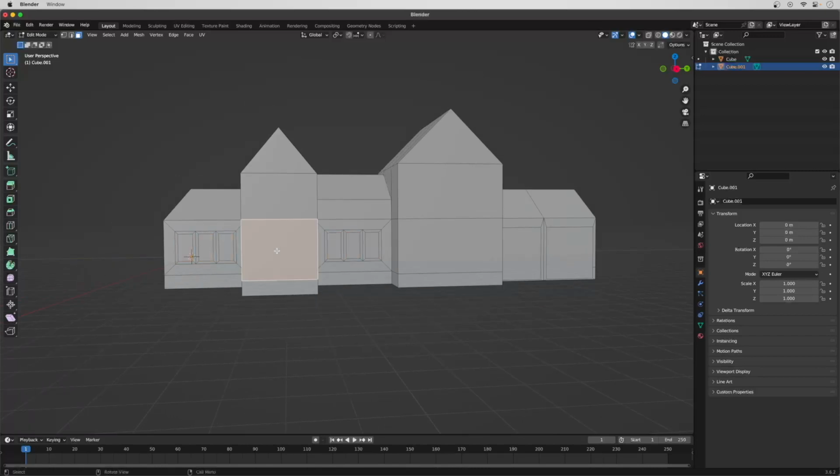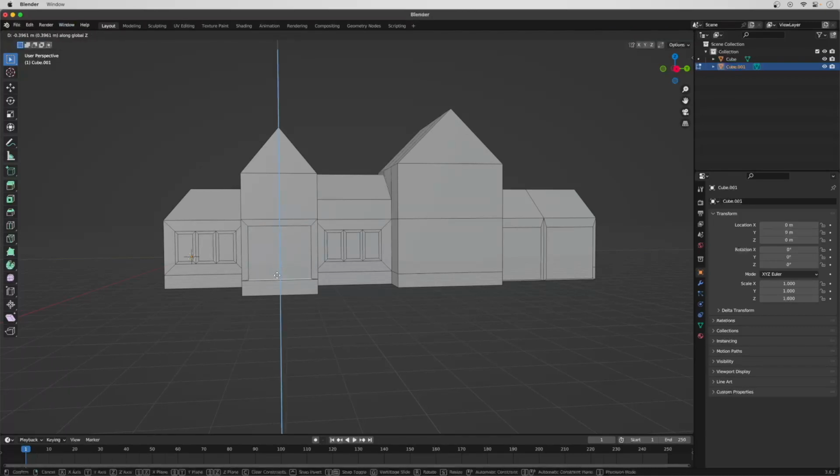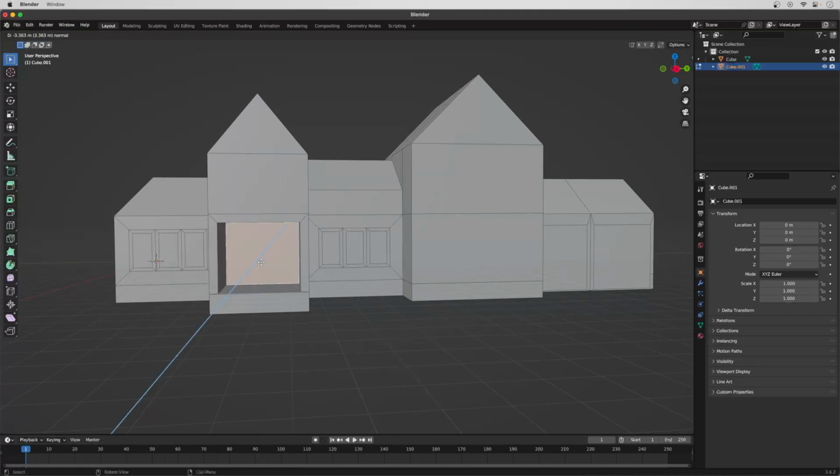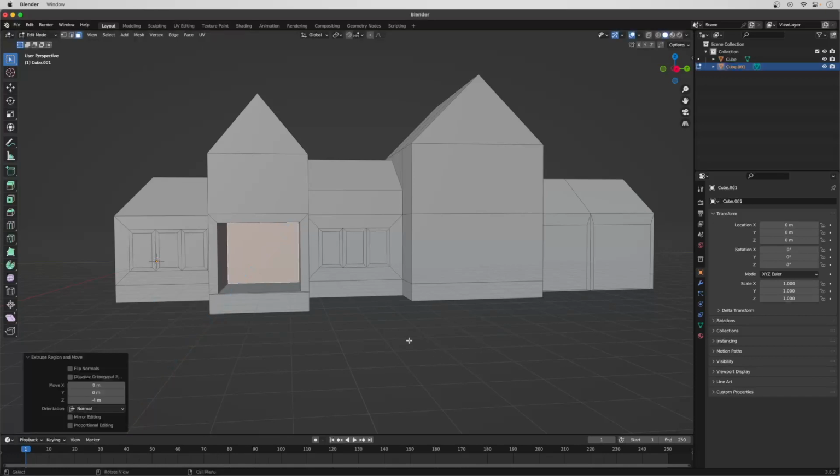Now I'm gonna select this one. I'm gonna insert face. You could click just I now. Now I'll go to Edge Select. Select this edge and I'll pull it down. So G on the Z axis. There, then I'll select this face and extrude it in by -4.